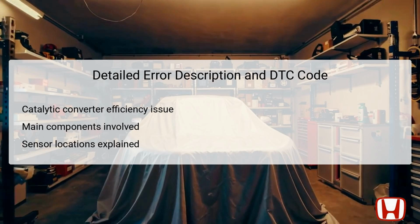If the secondary sensor shows a significantly different reading compared to the first, it signals that the catalytic converter may be malfunctioning. The physical location of the catalytic converter is beneath the vehicle, attached to the exhaust system, while the HO2s sensors are installed in the exhaust pipes leading into and out of the converter. Addressing this error quickly is vital for maintaining your vehicle's efficiency and passing emissions tests.